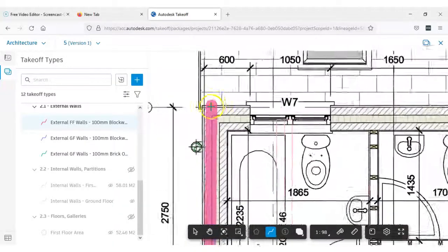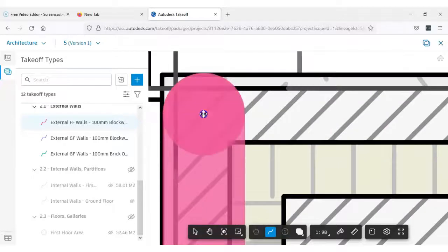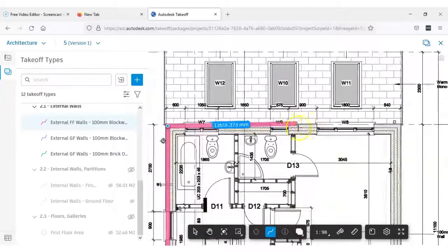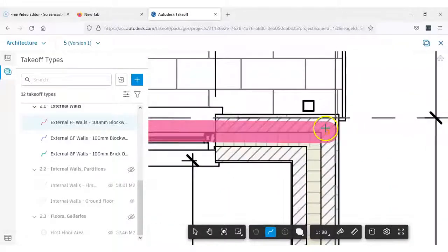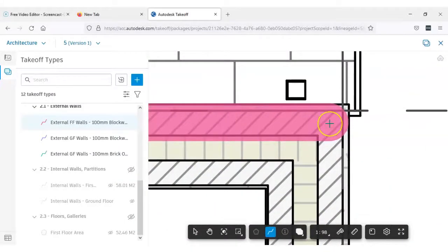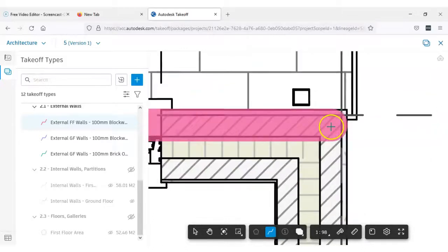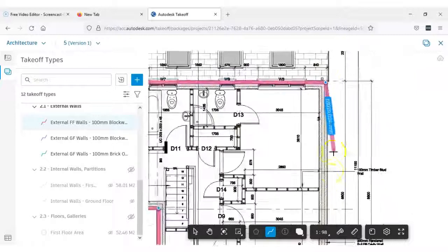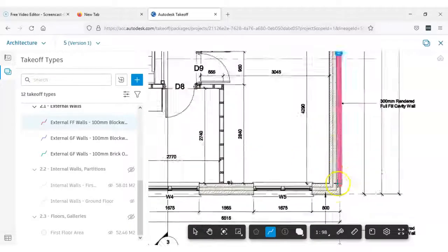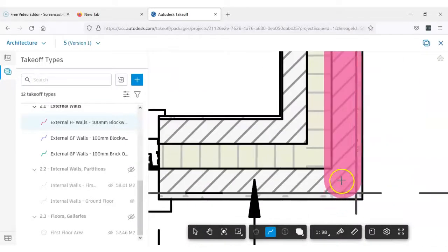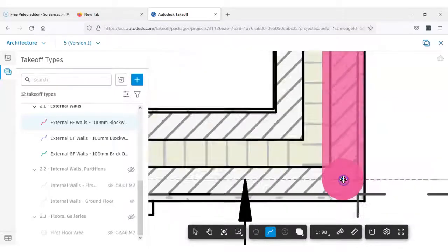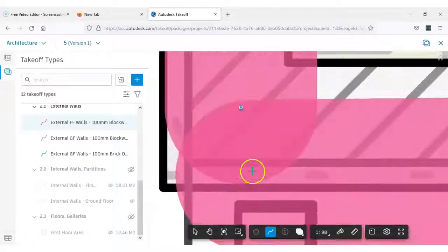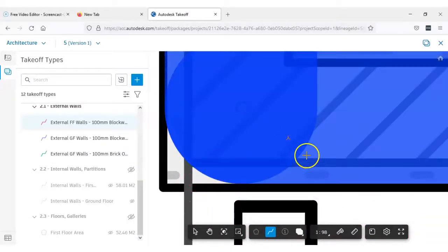You'll notice I'm measuring through windows. That's something I'll take out at a later time. I'm not going to stop on either side of that window, because then I'm saying that the window is full height, which it's not. Oh, zoom in. There we go. And you might find that this is the easier way for you guys to measure this. It's up to yourself. I would say better practice is the outside inside, and then I want to come back on that actual point. So zoom right in, click, turns green.